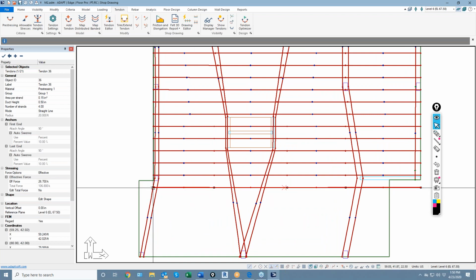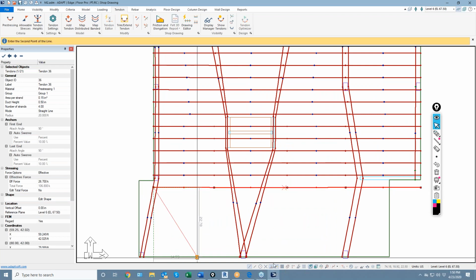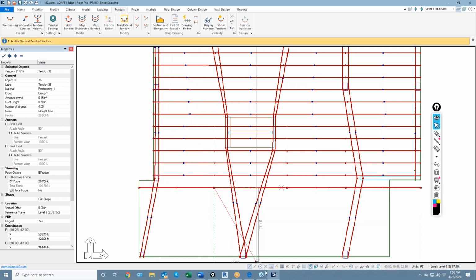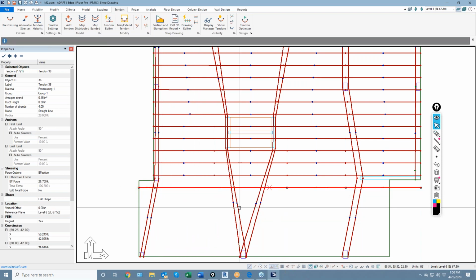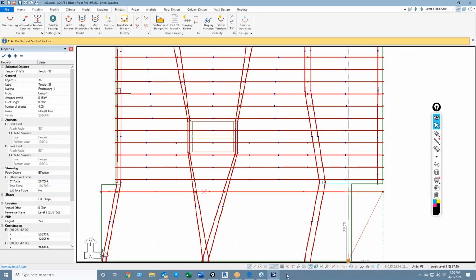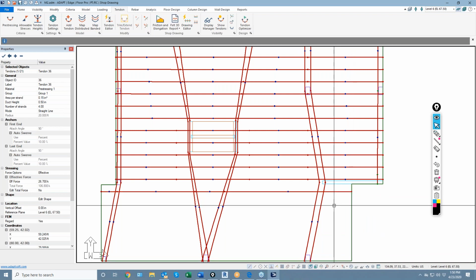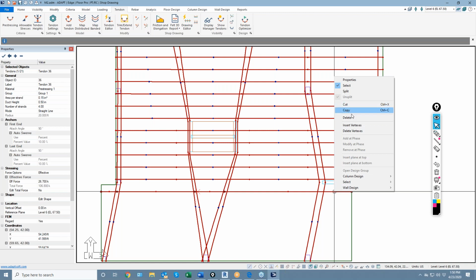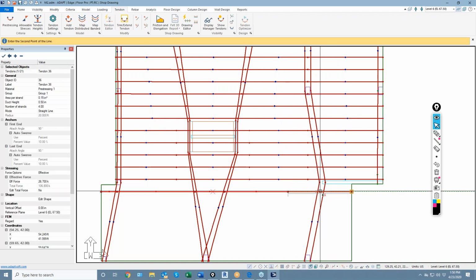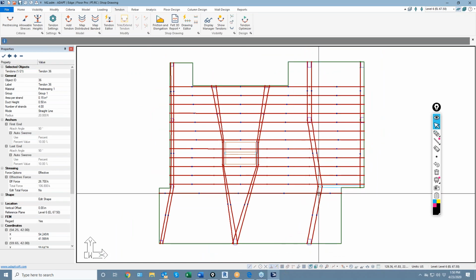Okay, let's go ahead and adjust, see if we can get through these cables. I'm going to go ahead and move these points over. I'll just move this over. I'll use this as another, this will become another primary tendon that I'm manipulating now. Let me save the file. I'm going to right click, insert a point right there and just move it over. So this is a new high point.